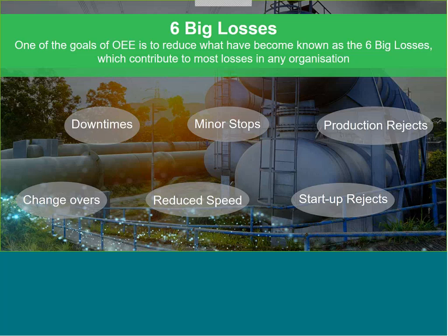Where you have machines that are designed to run at their maximum possible speed or production rate, it's often the case that operators might reduce the speed of the machine because they feel they get less rejects or waste. So it's important to capture those events, to build an accurate picture of your performance losses. Any time lost to changeover is also a form of downtime. So that could be machine changes for a new production, a new product run, or planned cleaning. So all of these losses together, they all feed into what are the key requirements for an OEE solution?